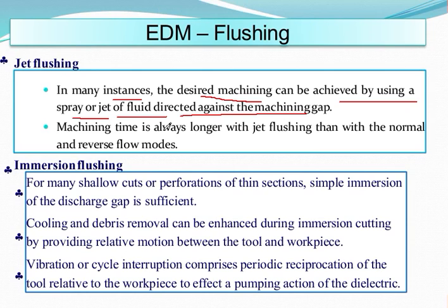And the most important thing is that machining time is also longer with jet flushing than with the normal and reverse flow methods. Or you can say the machining time is also longer with jet flushing in respect to normal and reverse flow modes. Now we will be discussing immersion flushing.